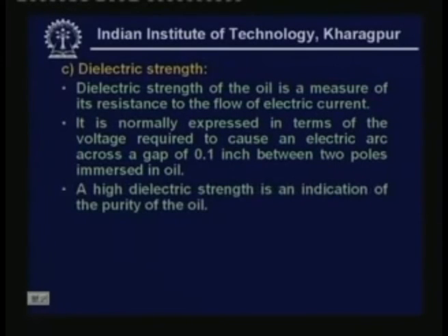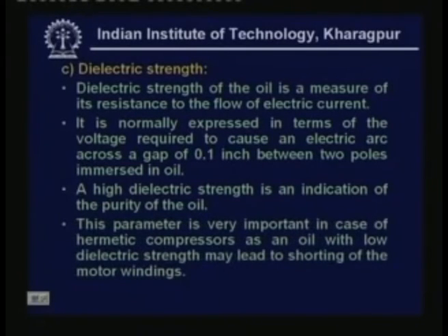A high dielectric strength is an indication of the purity of the oil. And this parameter is very important in case of hermetic compressors, as an oil with low dielectric strength may lead to shorting of the motor winding. So, we have to have refrigerant lubricating oils having high dielectric strength, so that the shorting of the winding does not take place.